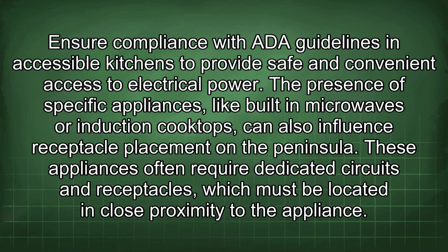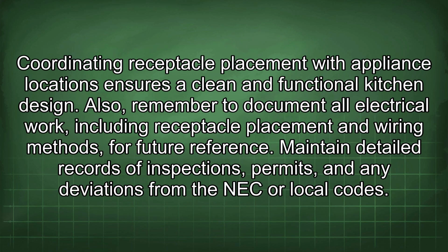The presence of specific appliances, like built-in microwaves or induction cooktops, can also influence receptacle placement on the peninsula. These appliances often require dedicated circuits and receptacles, which must be located in close proximity to the appliance. Coordinating receptacle placement with appliance locations ensures a clean and functional kitchen design.